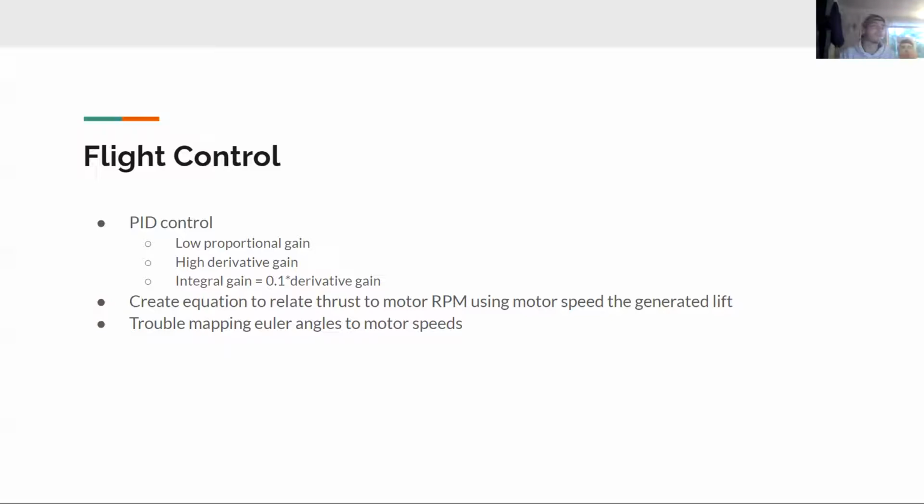So once it generated lift, I was able to reverse the equation because I could relate the motor speeds I commanded to the force needed to generate lift for this drone, which is just its mass. So the force is F equals ma, mass times acceleration due to gravity. I was able to do the math to find the proper K constant.